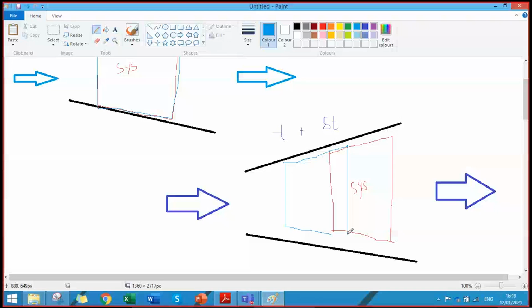Why is the control volume fixed? Because we have defined it ourselves. We say it's fixed. But the system was also defined by us. But system is about a fixed mass. System is like tagging a particle. I have tagged a specific mass, and I will keep following that mass. That's the Lagrange approach. But in control volume, we have defined it is fixed at its place. Mass can enter this control volume, mass can leave this control volume, but it will remain fixed at its place. So clear?